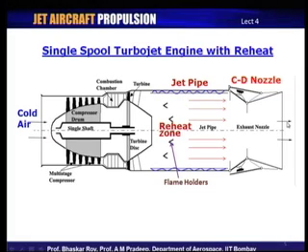On the other hand, the higher this velocity is going to be, the higher is the exhaust gas energy with which it is going out, which means typically that the waste energy that we have talked about in the last class is also going to be of a higher order. So, a typical reheat engine or afterburning engine would invariably have very high waste energy intrinsically associated with its performance, and which of course also means that its efficiency of operation is going to be somewhat on the lower side.